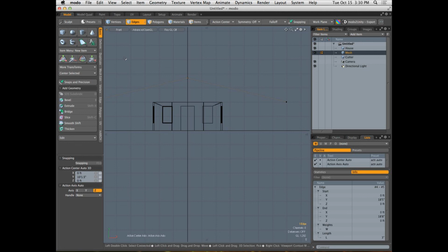What are you getting when you do the slicing? I have a hunch. Aha, yes. I recommend whenever you're using the slice tool to be inside of an orthographic viewport. If you're in perspective, slice gets real conceptual pretty quickly. It turns into this really weird plane, and it's very difficult. Let's check it out.